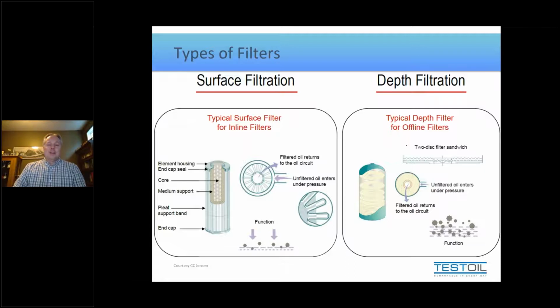With a depth filter, you essentially take many pieces of media and you stack them on top of each other, which is why we call them a stacked filter. But now the oil runs through that media lengthwise. So it goes through the depth of the media. Now, either filter can be made with either type of media. Those are options that are available. So it's not to say that all pleated filters are paper, nor saying that all depth filters are synthetic. It could be either way. But predominantly what we're looking at is that with a surface filter, we typically use these in full flow applications, meaning where most of the oil is going to go through and is delivered to machine parts.